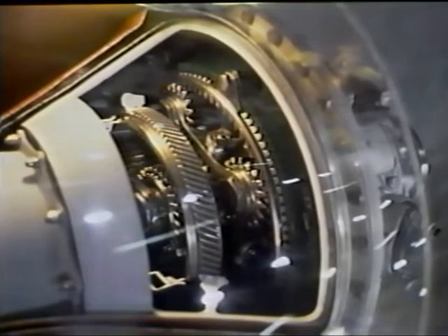But when more power must be carried to the propeller than can be transmitted with the simple gear arrangement, planetary gears may be used. This arrangement keeps the propeller shaft concentric with the crankshaft and does not reverse direction between the two shafts.